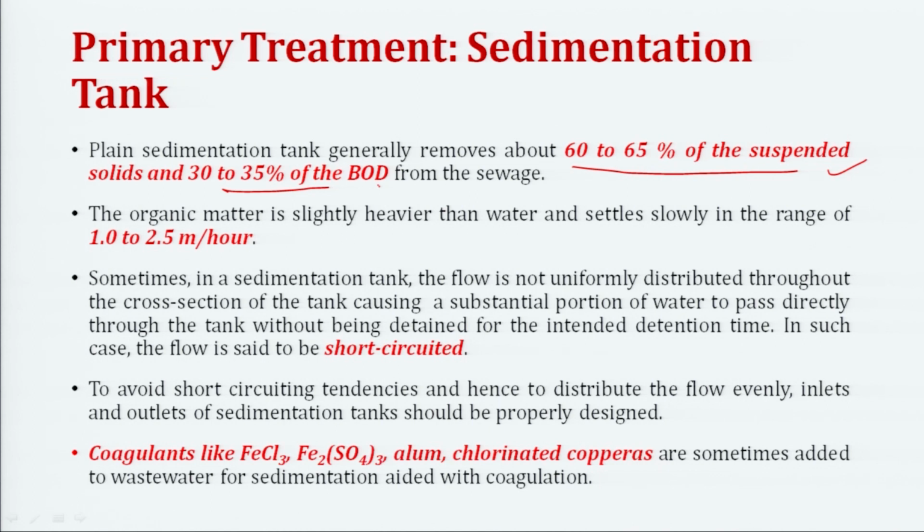The organic matter is slightly heavier than the water and settles slowly in the range of 1 to 2.5 meter per hour, right. For inorganic, which was in the case of grit chambers, the settling was much more. Why? Because the density was higher, right. But here the organic matter is only slightly higher than water, maybe 1 plus something, the specific density, right. So, then there is another concept called short circuiting here.